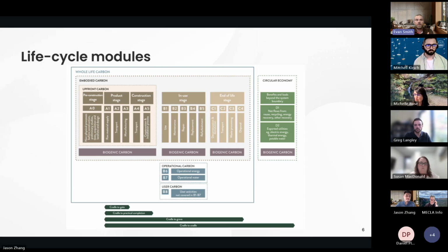So I think EPD is valid up to 5 years, but if EPD is available on EPD Australasia and international, it has to be valid at all times. So if it's still there, it means it's valid. So as a user, we have to keep reviewing it and make sure that number is still representative of the published one, so the actual matches it with no more than 10% variation as well. So if it's up, it has to be valid.